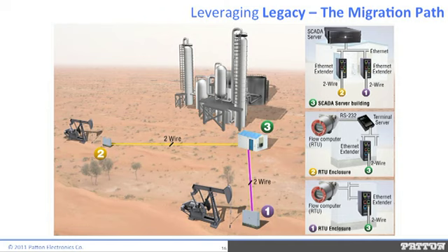And as Johnny will explain shortly, a highly recommended solution is the use of Ethernet extended products over an existing single twisted pair. The last step of the solution is to insert a device server between the flow computer and the remote Ethernet extended device. Incremental step number two.